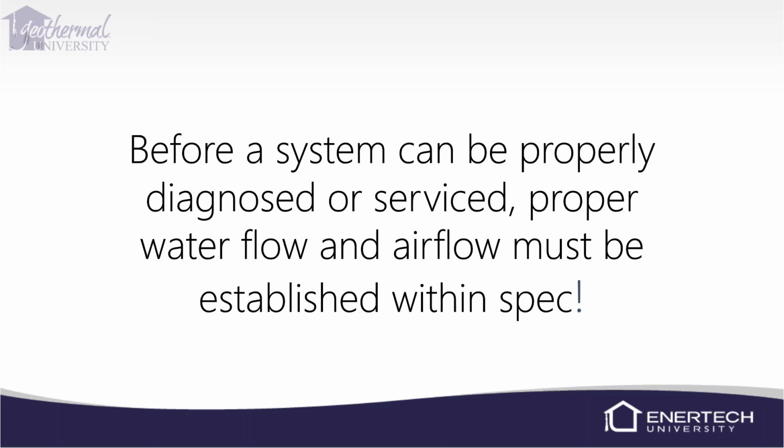So if you're supposed to be moving 1,240 CFM, it's going to flash 12 times and then do a little crazy flash to let you know it's getting ready to start over. So it'll tell you basically 1,200 CFM, because it's not going to give a half flash for the 40 CFM.